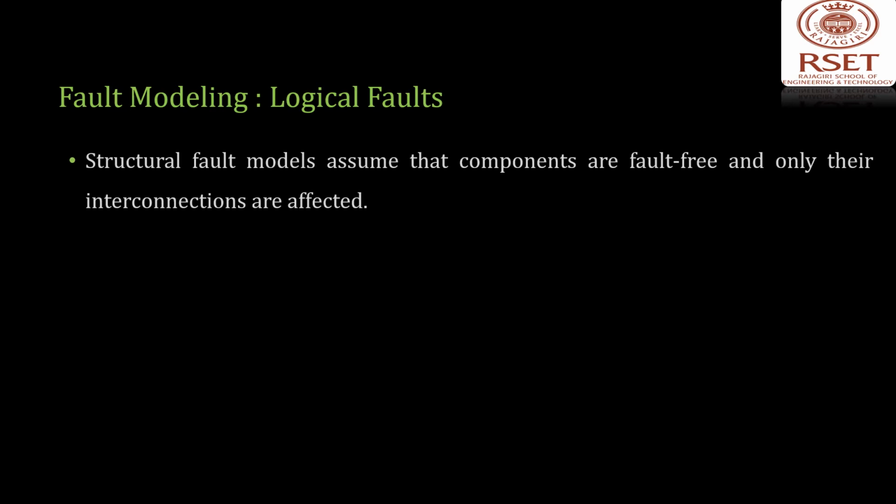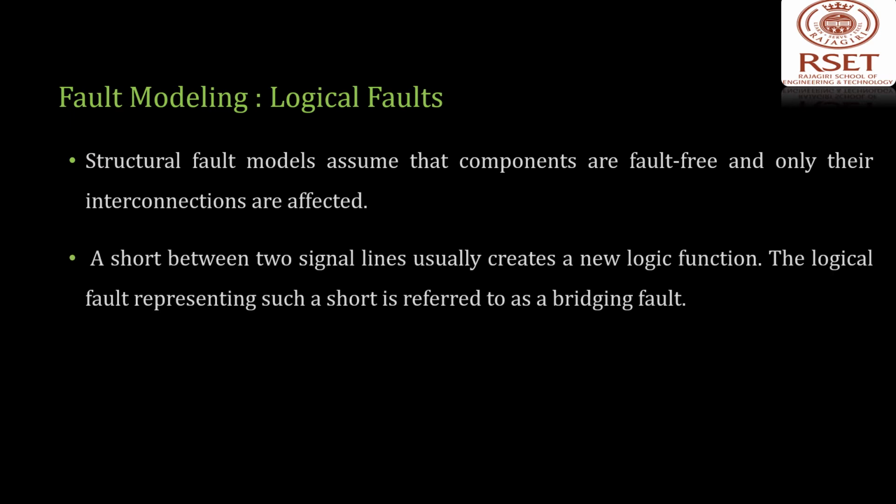Now let's discuss structural fault models in logical faults. Structural fault models assume that the components are fault-free and only their interconnections are affected. Now, how can the interconnections be affected? In a logical circuit, the interconnections are affected either by shorts or by opens. Now, what do you mean by a short from a digital point of view? A short is formed by connecting points which are not intended to be connected, whereas an open results from breaking of a connection.